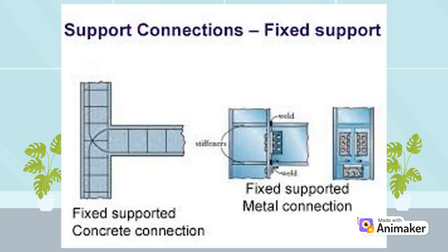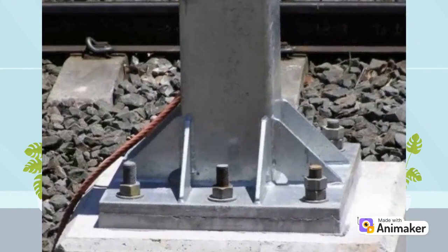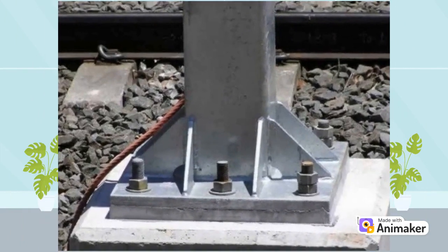The application of the fixed support is beneficial when we can only use a single support, and it is most widely used as the only support for a cantilever. They are common in beam-to-column connections of moment-resisting steel frames and beam, column and slab connections in concrete frames.